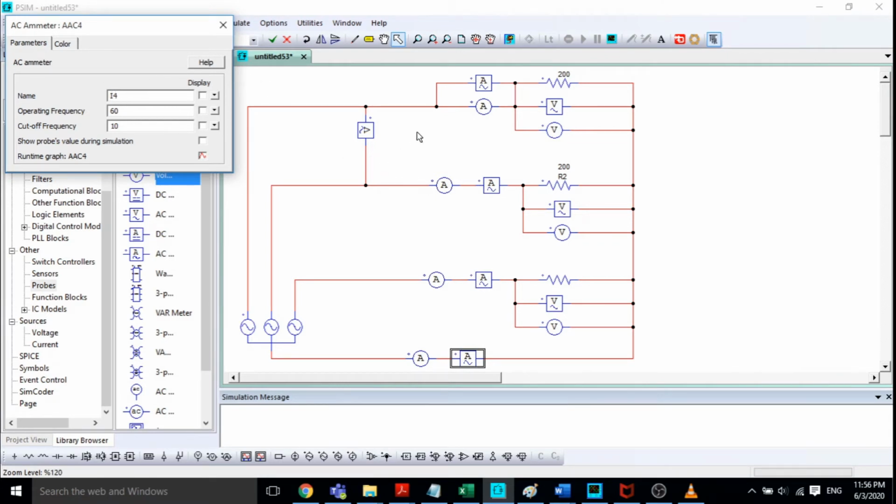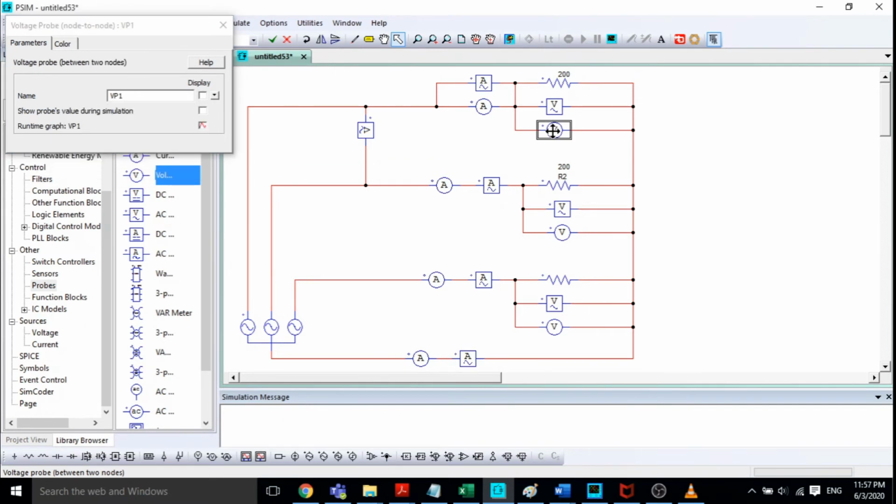Now, what names to use for the waveform, voltage, and current meters? Well, in this case, I will basically use the same convention, adding just a W in between the first letter and the number, and that way I know this is the same as the AC but in waveform. So for example, this one will be named EW1 and EW2 and so on.